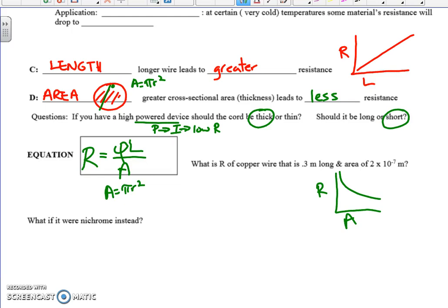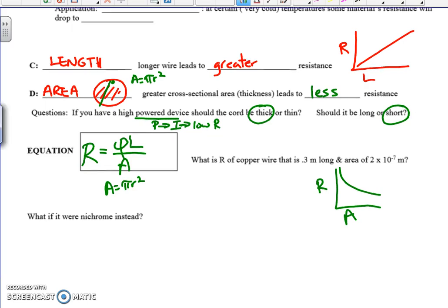And you might wonder, where's temperature in this? Okay, so temperature is a little bit complicated, but essentially the value of the resistivity is temperature dependent. So if you go to your reference tables, it'll say the resistivity at 20 degrees. Okay, so all our equations using resistivity are assumed to be at room temperature. What you have to know about temperature is conceptual. If the temperature goes up, understand that R goes up, and then current is going to go down, etc.